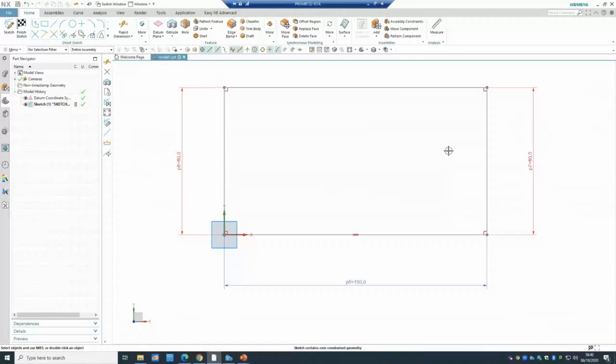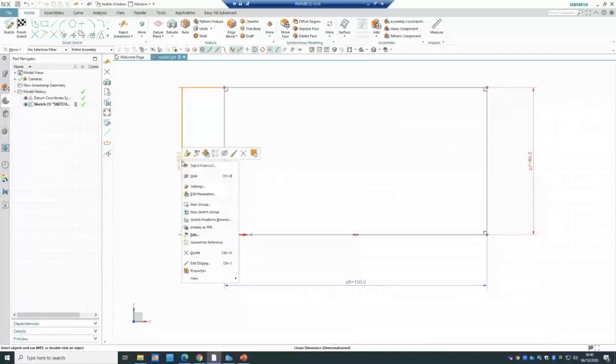And even for the assignments, they make the same sort of mistake. Please make sure whenever you see those red, it matters. You may sometimes put a dimension, and it happens to me as well, and it says, okay, it's over constrained. You need to find out what the reason was that made it over constrained. So you can always come back to that one and delete it.